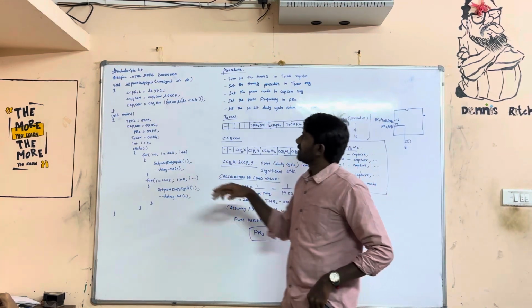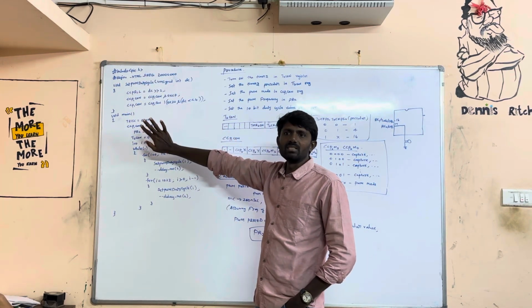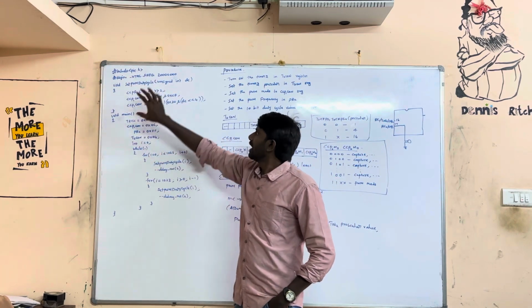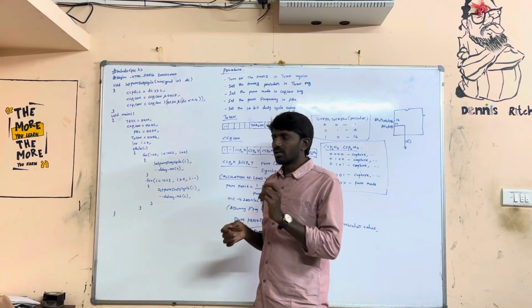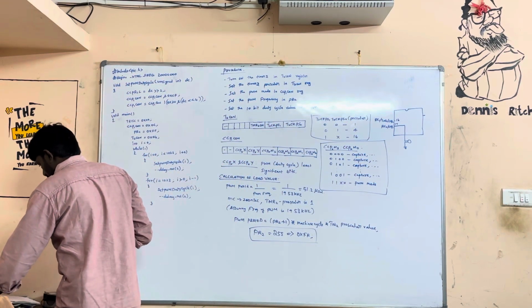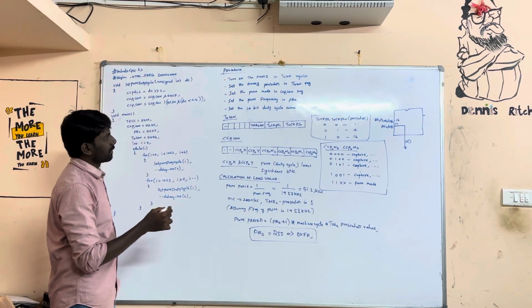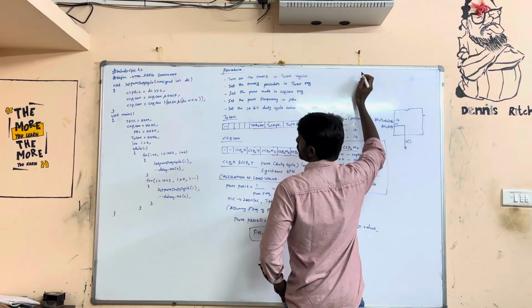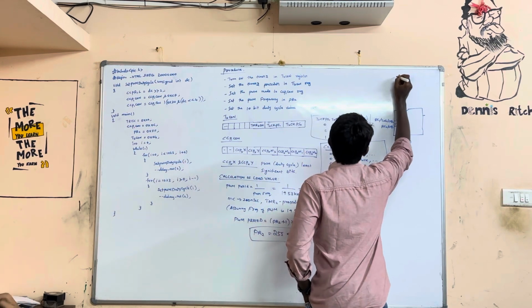So for that, coming to the program, you have these two lines, no interrupt in this. Okay, just straightforward. These two lines already we know, and this is one function. What this function does is, the duty cycle is how many bit value? It is a 10-bit value, correct? So 10 bit means how many registers? Two registers we need. Okay, so these two registers are CCPR1L.